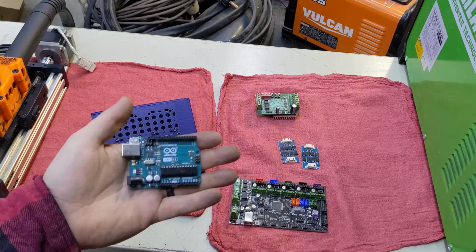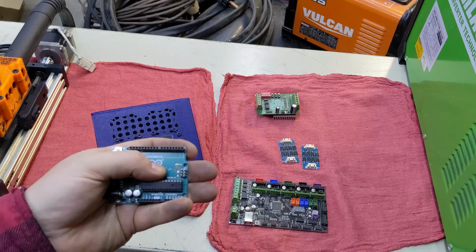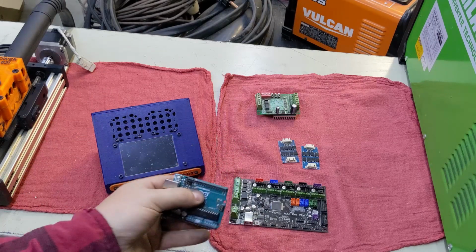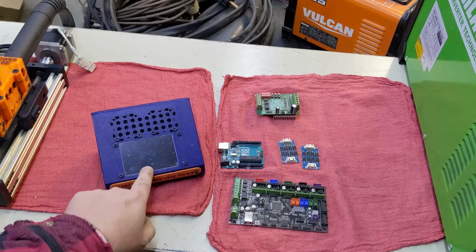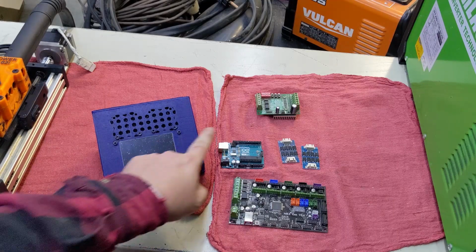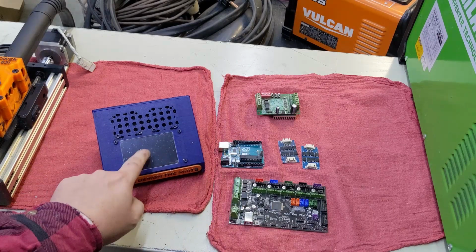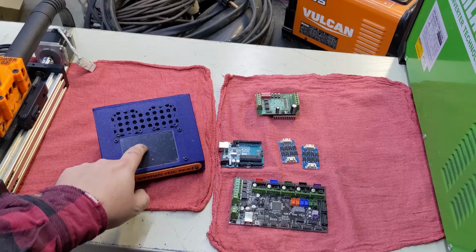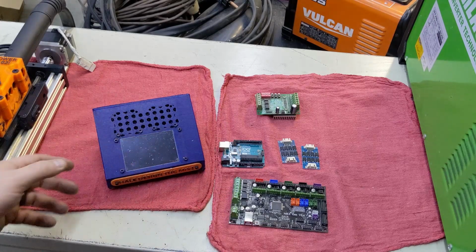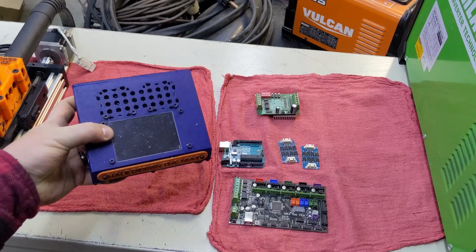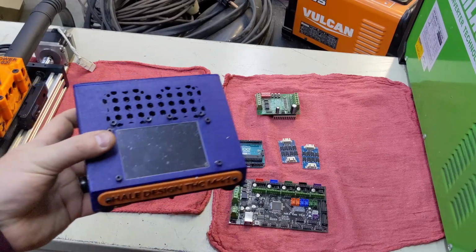I initially used this Arduino, ran everything off of it, and it seemed to work pretty well. But there is a connection lag between inputs on the screen to inputs on the Arduino. Sometimes you got to hit a button 3 or 4 times on the screen before the Arduino finally realizes you want to do something. So the Nextion screen interface is not perfect.